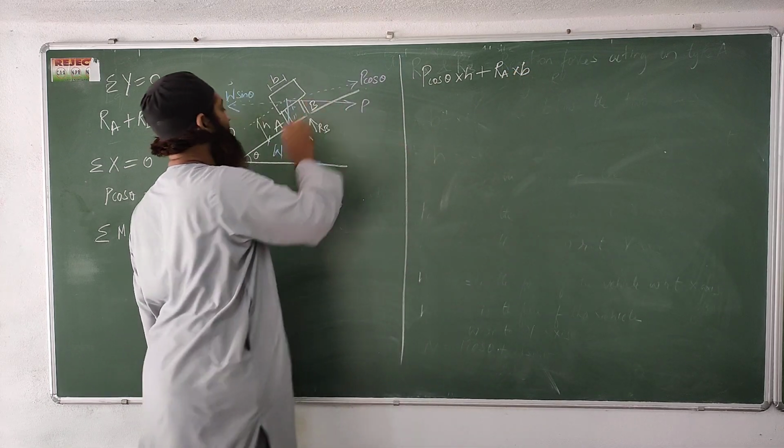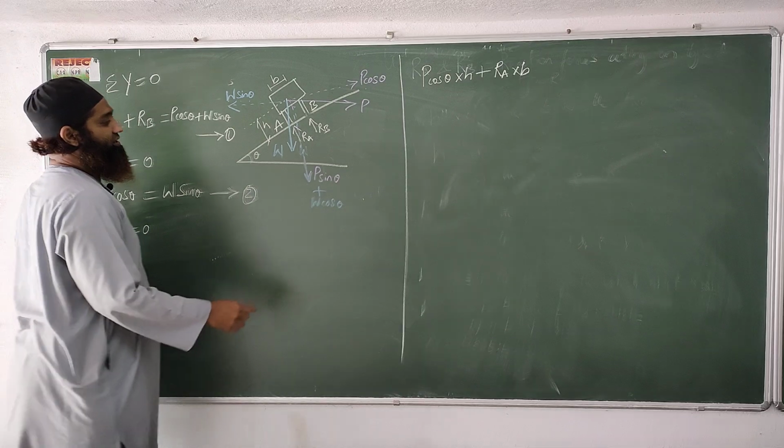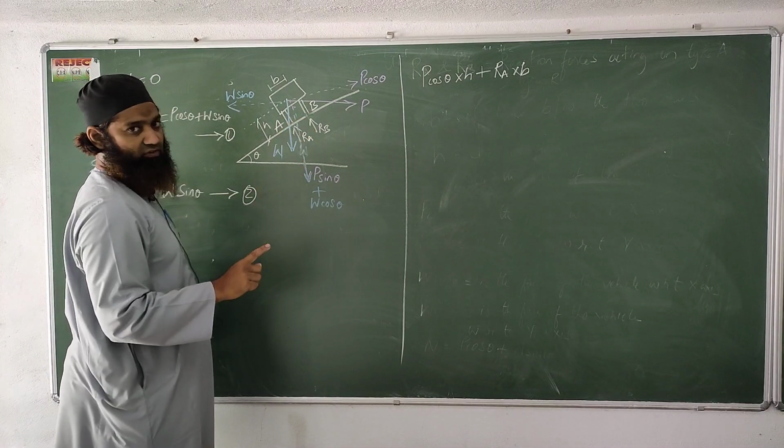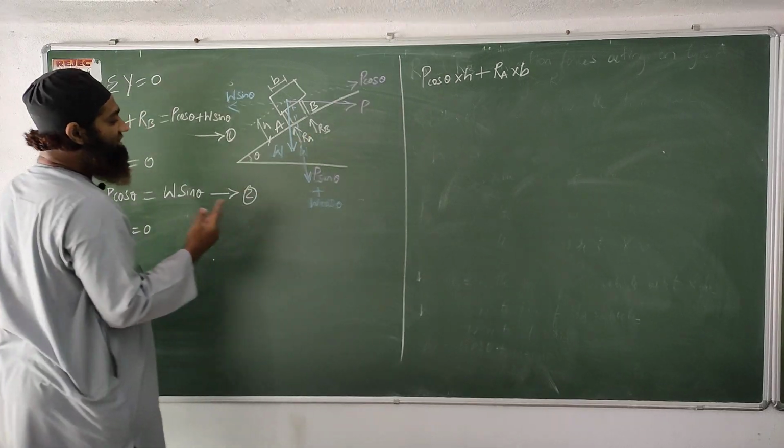Okay, these two forces are acting in clockwise direction. So I have written this. I have one more force here. RB will be directly acting here, so its moment will be 0. We won't be considering this force. What are the other forces that are left?